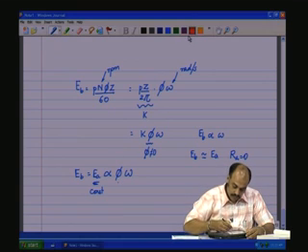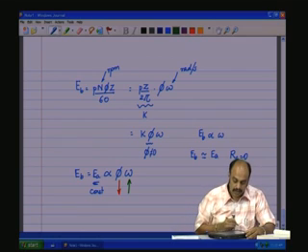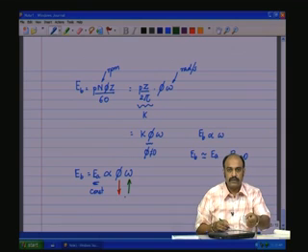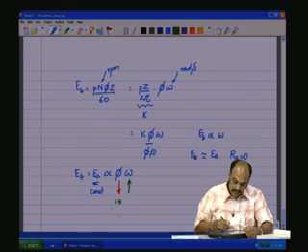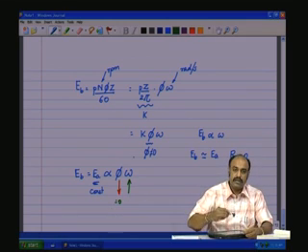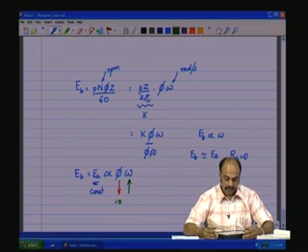If you reduce the flux, the speed is going to increase so that the product is a constant. So if the shunt field winding coil is suddenly made 0, then under no load conditions the speed can increase phenomenally high, and it may break away and damage the machine.